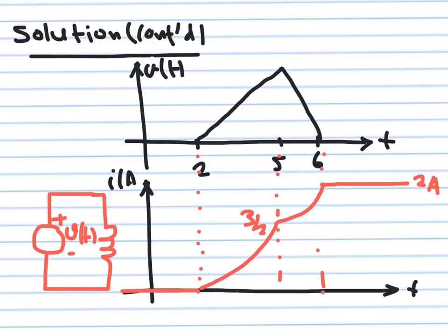So now if you want to check the voltage and the current, this is a given voltage. It's rising up to 2 and then going down from 2 to 0. You will see that before that the current was 0 because there was no excitation. Just let me backtrack. This is how the circuit looks. Now we are applying a voltage to the inductor, and we would like to calculate the current flowing in the inductor. So this is my target here: find I of t.